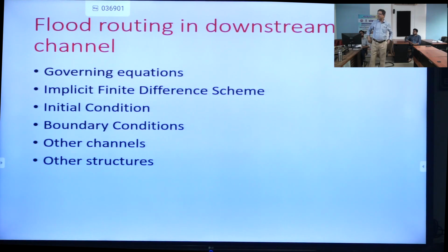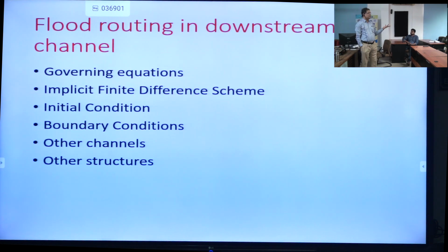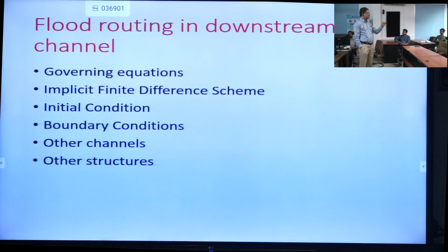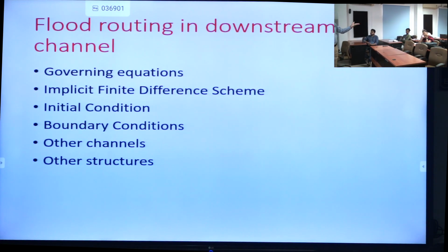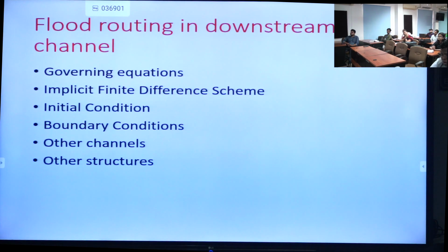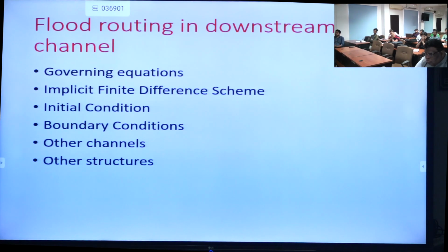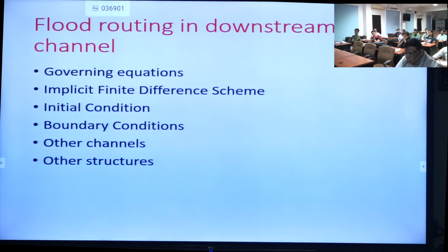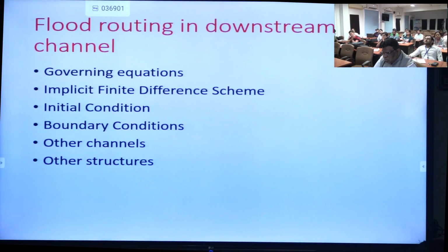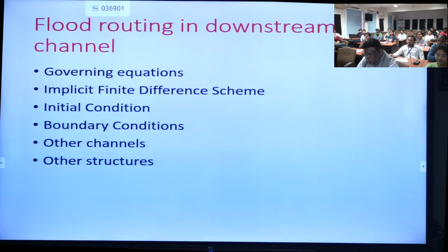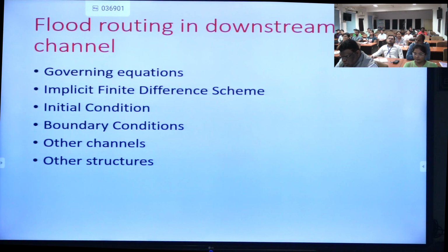Most appropriately, if there is a measurement station, a gauging station, then use the measurements from that site. Or if there is a locality where you have the rating curve, for different locations we develop rating curves, which is discharge Q versus H, H versus Q. If you know that, there are several options in the menu in the program.